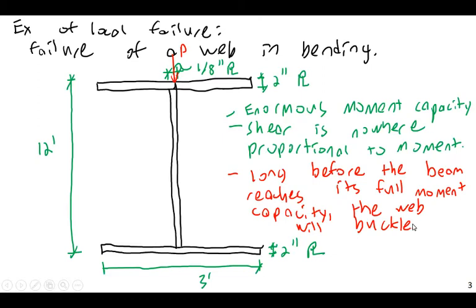And let me explain why that is. At first, I don't know if this seems odd to you, but it always seemed a little bit odd to me. The reason it seems odd is because you might think, wait a minute, how can something buckle? It's not a column. I mean, it's clearly attached all the way along, so shouldn't it be able to disperse load up and down the web? It's not a standalone column. When I draw it this way, it looks like a column, but how can this thing buckle? It's a long plate. So how does it buckle? Well, let me illustrate how loads and stress will actually distribute within the web of a beam here.